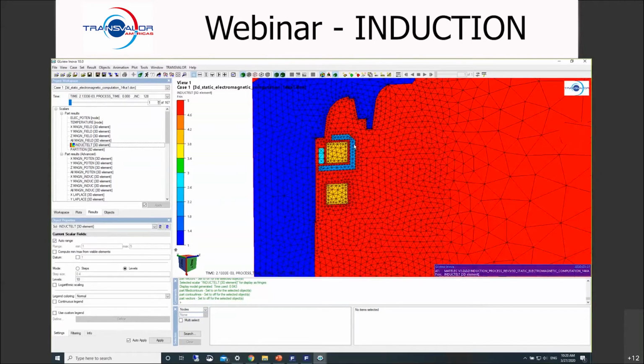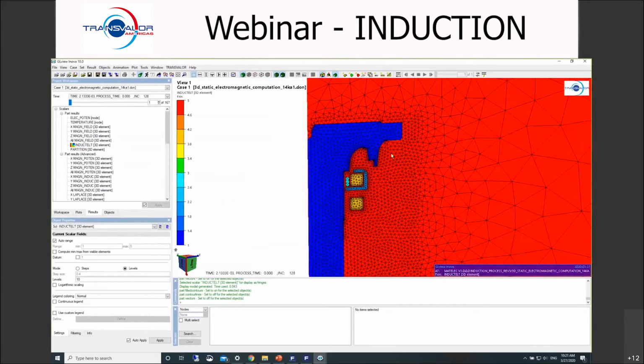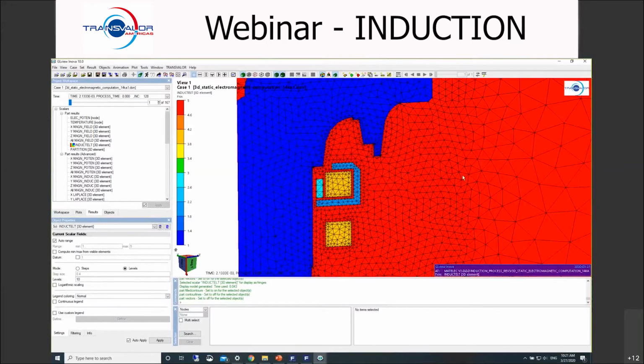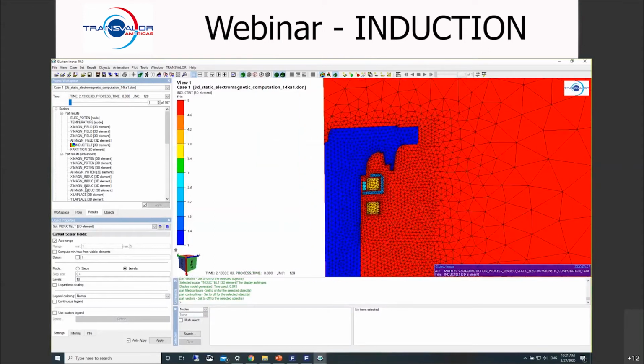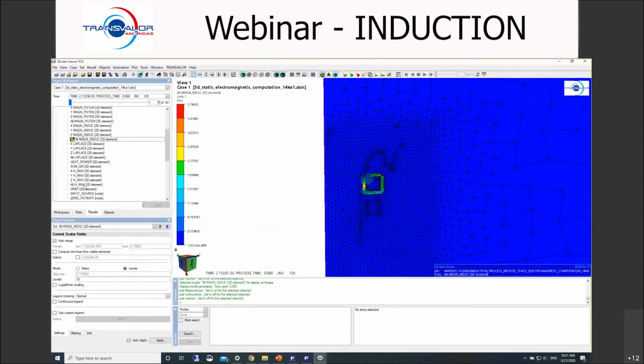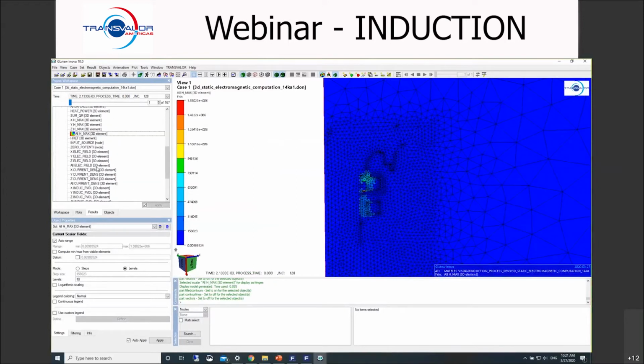You'll see that in the global mesh, every element and every node is assigned to a different object. For one, a value of 1 means billet, a value of 2 means this concentrator. Every object has a number, okay? Even if it looks like we have one object, we have all the objects defined. It's just shown in a unique mesh. Here we'll have all the magnetic results. I don't have a lot of time to get into them, so I'm just going to quickly show them.